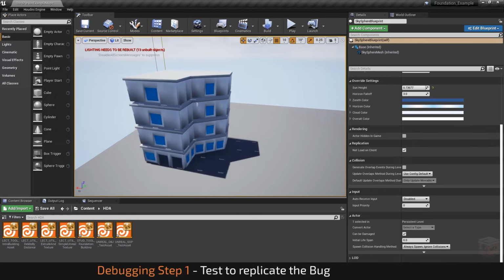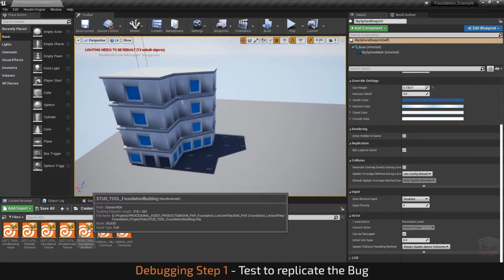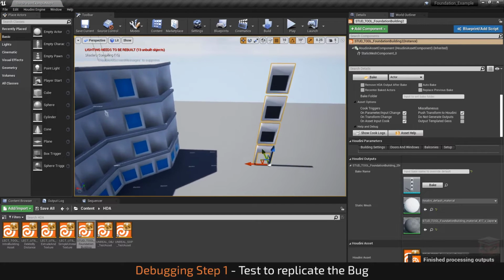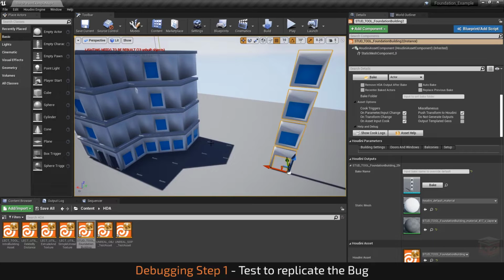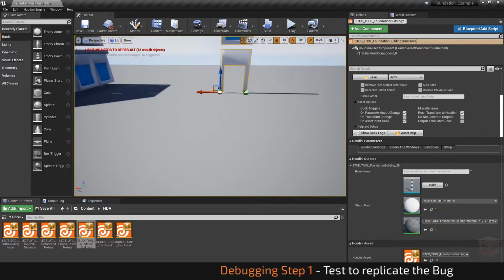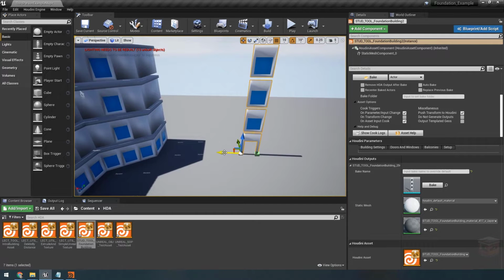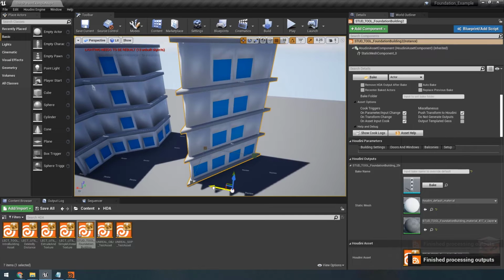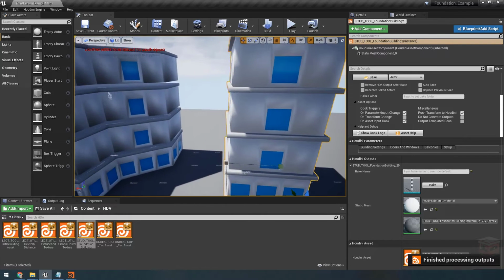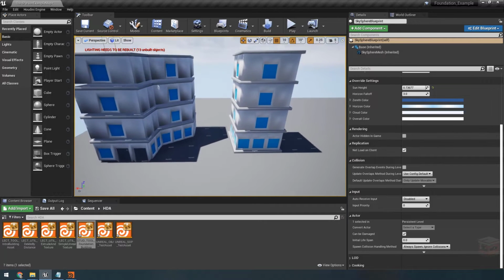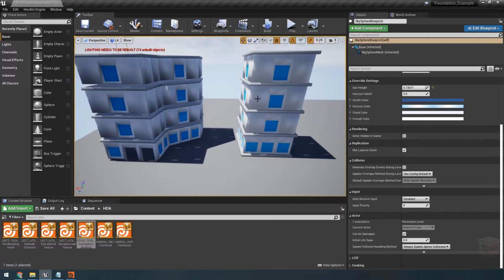And we can quickly test this if we just grab another building and recreate the situation, but instead of drawing our curve in a clockwise direction, let's draw it in a counterclockwise direction. Let's grab the curve, drag it out, hold Alt, and here we go. Okay, so here our building is actually working properly. So it is the drawing order of our curve. Okay, so now we know that that's the problem.